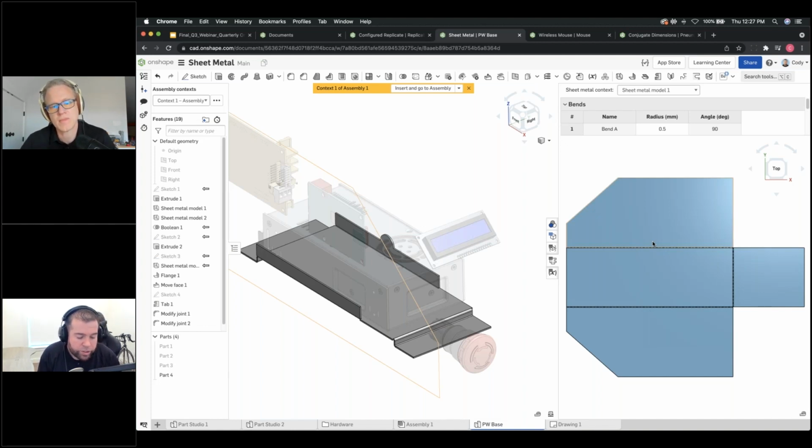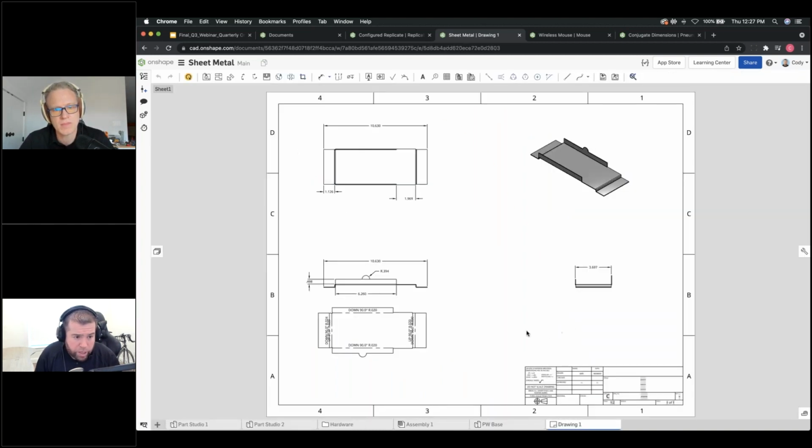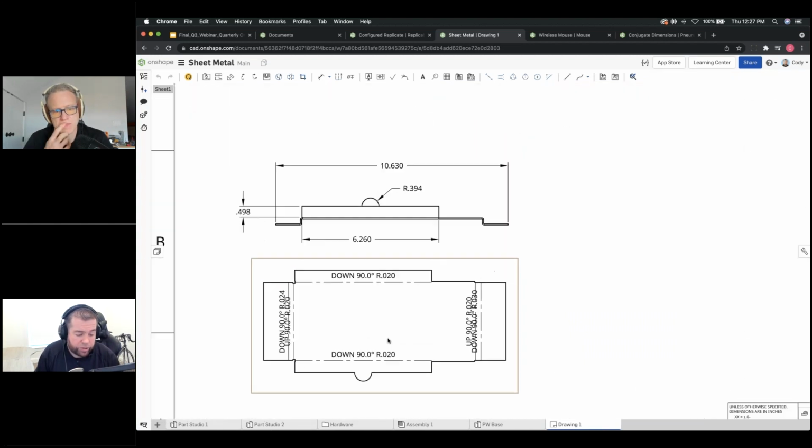But one thing that's always come up is how we display those sheet metal parts at the drawing level. At the drawing level, you have your sheet metal flat view that's inserted, and you have your bend notes that are defined. And in the past, the bend notes and the bend direction, more importantly, were a fixed thing. And so if the way you wanted to bend your part meant everything was essentially inverted, all of your bend notes would be exactly opposite of what they should be. And this sounds like a small thing. All you're doing is changing up to down. But when you hand this to someone who's going to manufacture that, it makes a world of difference. Up and down is a huge, huge difference.